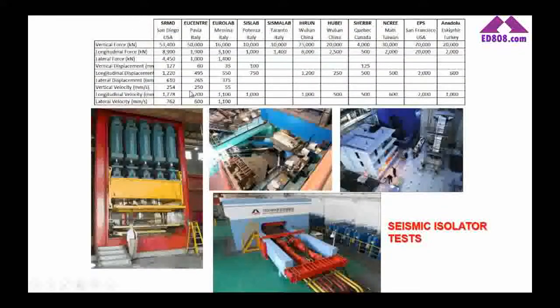The different thing in isolated building design is that when you do a conventional building design, what you do as a test is you only take some samples in the site, you cure them in the laboratory, and you do some compressive tests. No? Do you think that this is enough to understand the situation in the building? I don't think so. For seismic isolators, since these are crucial elements for the building performance, what we do, we test them.